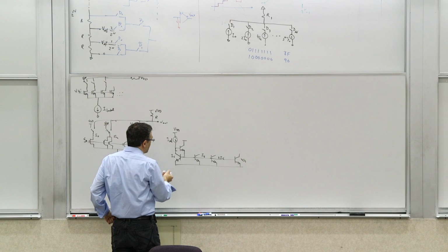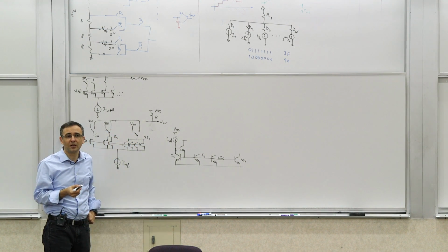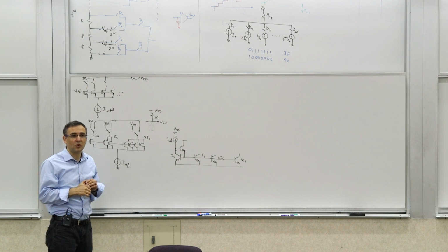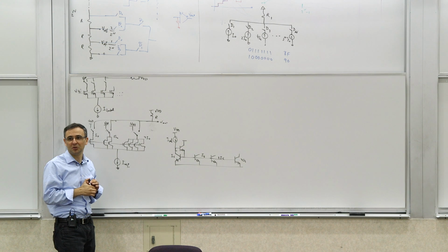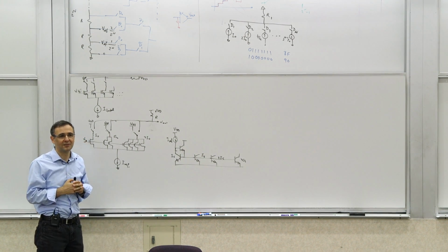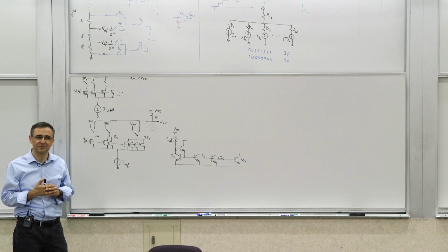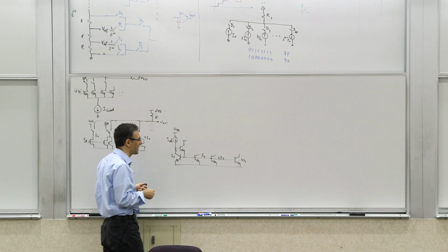Now, what else? Is this good? Do you think this is going to work? Or are you going to run into the motor driver problem that I described to you a long time ago? You remember thermal runaway? You remember the VBE had a negative thermal coefficient, so one of them gets a little bit warmer, the VBE becomes smaller, so it basically draws more current, gets hotter, more current, more hotter, and all those things. So that's going to be a problem.